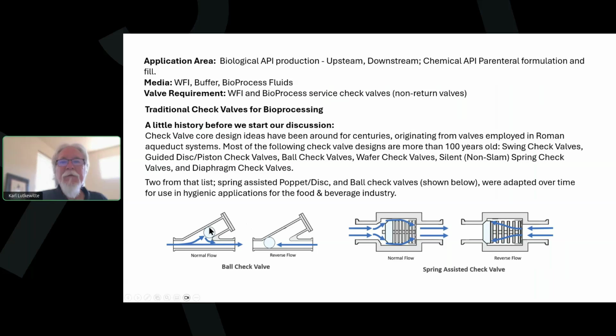And it's basically a ball that sits in the waterway. And if flow comes in through the inlet here, you can follow my cursor, it'll push the ball up into this little cavity that you see. The valve is shaped like a piece of Y tubing, but it's that simple. Flow comes in, pushes the ball up that cavity, and flow goes straight forward and straight through the valve.